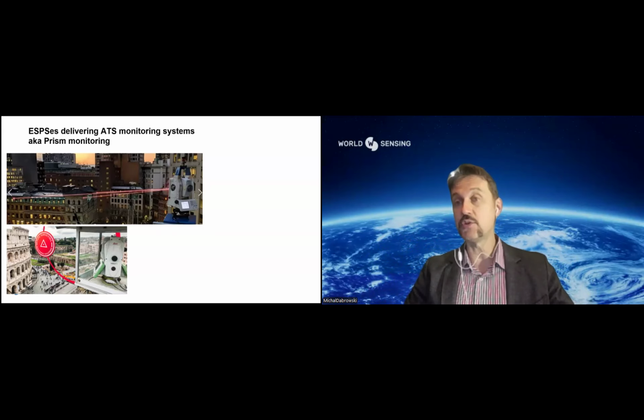They use an optical way of obtaining the distance and angle from your instrument to the prism. This is a very good technology for obtaining coordinates. However, with longer distances and changing weather conditions, it might be quite difficult and troublesome.